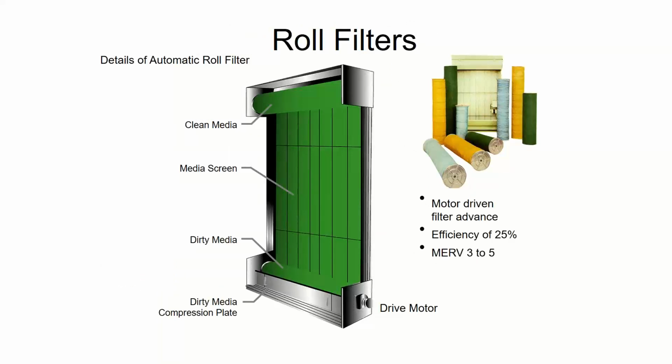Roll filters, which you're hardly ever going to see anymore. I think I've only seen one of these. They were briefly popular and then immediately gone. They got popular briefly because the idea was you can wait years before changing them because they automatically change. Every so often, this little motor turns, which scrolls more of the material through, right? It automatically changes. It's self-changing, if you will.